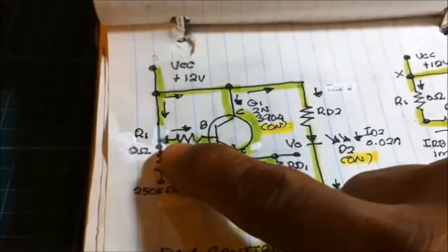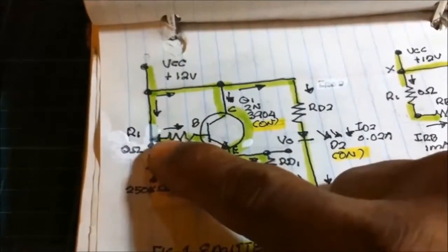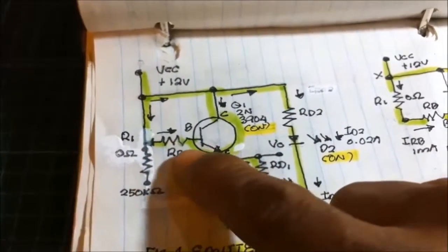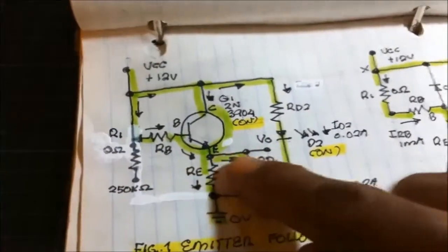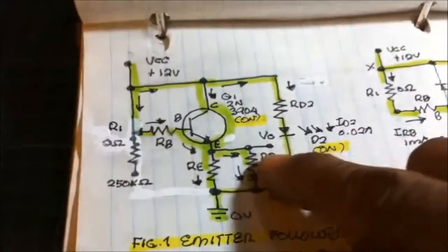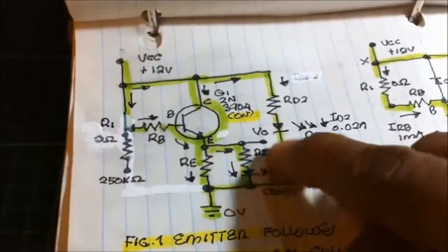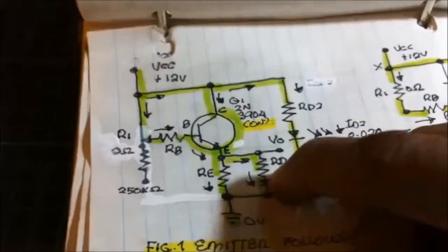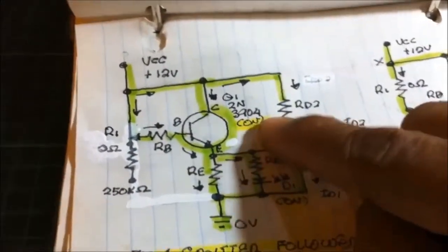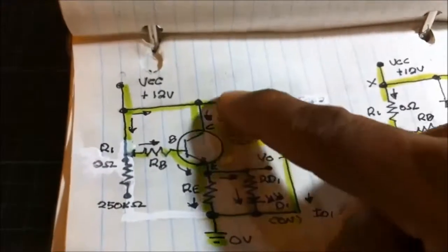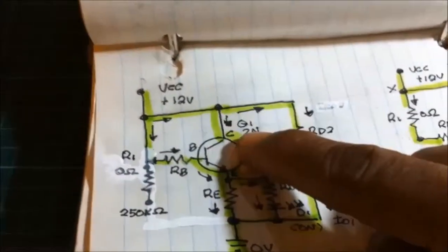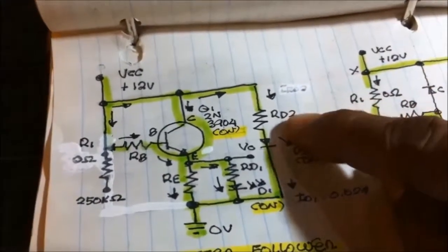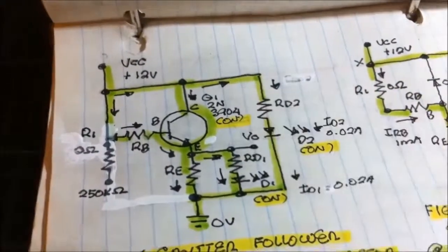I'm setting the potentiometer into the 0 ohms range. And then the base is now here, the emitter to the ground, and the emitter is in parallel with our output LED, and this transistor 2N3904, the collector, it has no resistor. That is my design. And this one is the power LED.